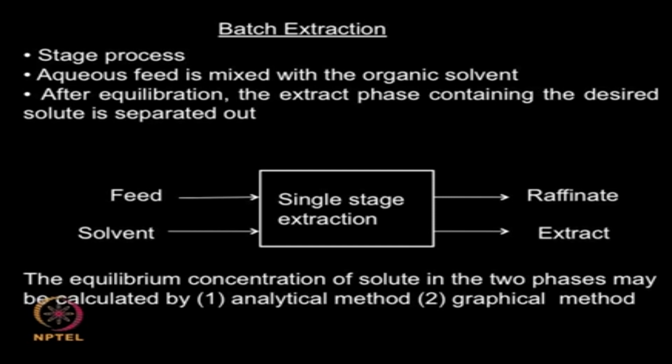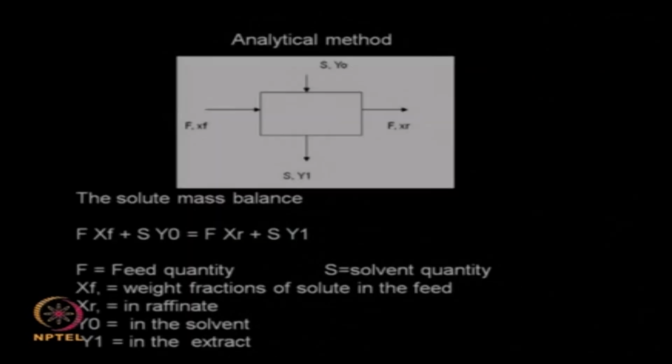So, we can calculate the equilibrium concentration of the solute in these two phases. We know the concentration entering in the feed, and after the extraction we will be able to calculate the concentration in this as well as in this place. There are two ways by which we can do this. One is called the analytical method, the other is called the graphical method. Let us look at the analytical method.